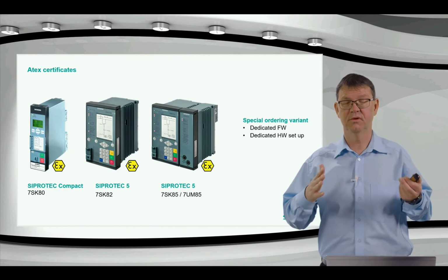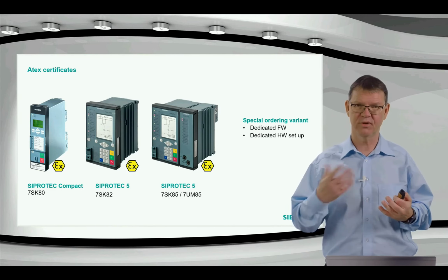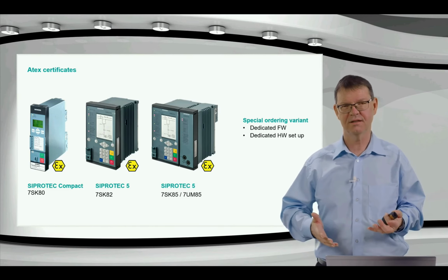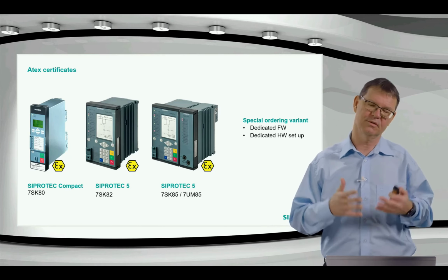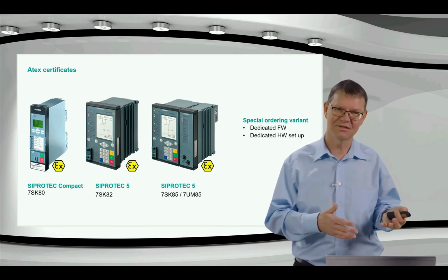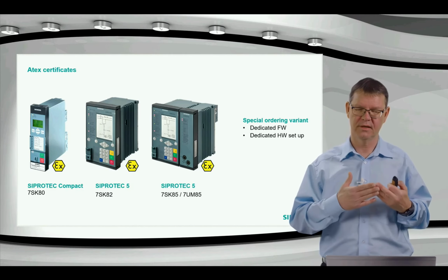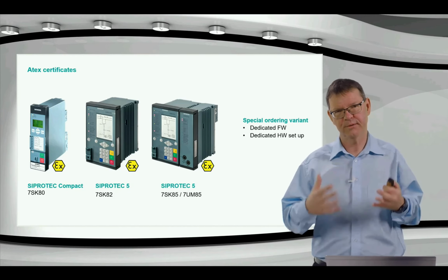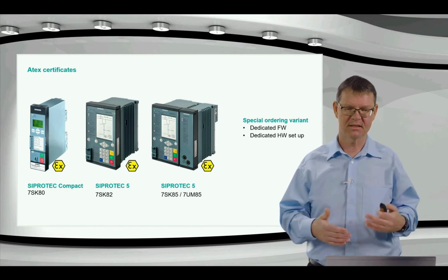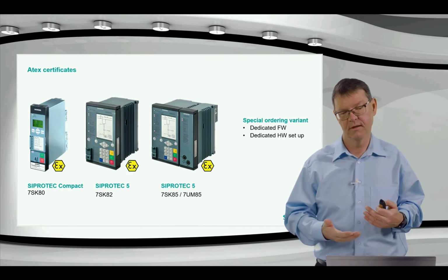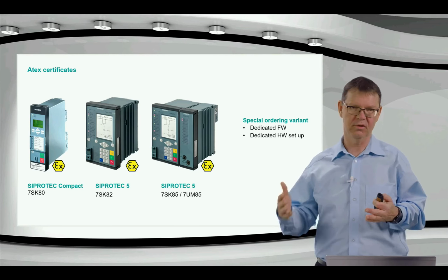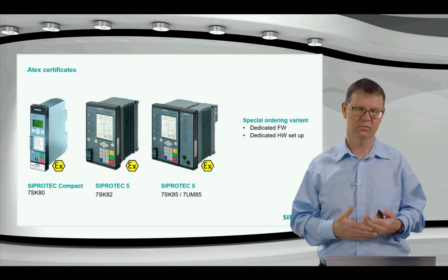And so you cannot just take a device and upgrade the firmware, because then you lose the ATEX certification, or the device you have does not have this ATEX certification anymore with a new firmware. And also if you change the hardware setup, and it's a hardware setup we have not tested and calculated and proved, then you're also falling out of that ATEX certification range.